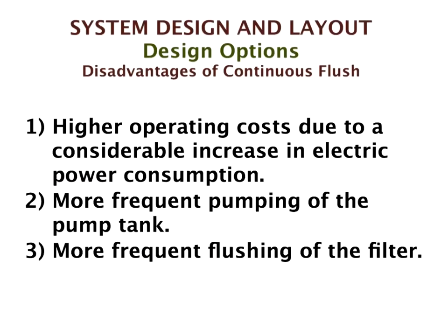More frequent pumping of the pump tank, because you've got this water going round and round, and it's going to increase the amount of solids in the pump tank instead of that material going back into the treatment plant to be retreated. So the solids are going to build up more rapidly, and you're going to be disturbing the pump tank with the extra flow of water going around and round, unless you have a settling tank, and then you haven't saved your capital expense.